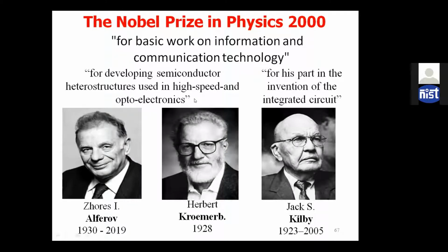Nowadays, we are getting very high speed data due to optical communication, and the main part is that you convert the electrical signal into optical, or optical into electrical. That means the ILD, injection laser diode, whose efficiency developed a lot after the development of semiconductor heterostructures. So that's why they got the Nobel Prize.